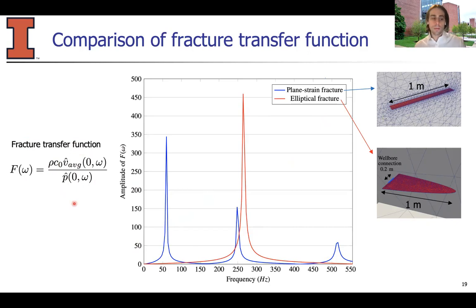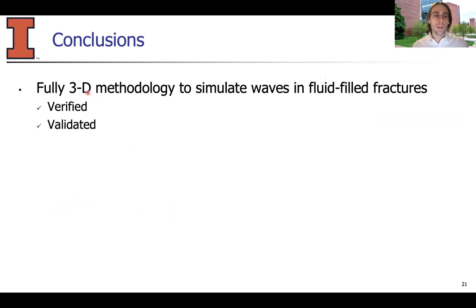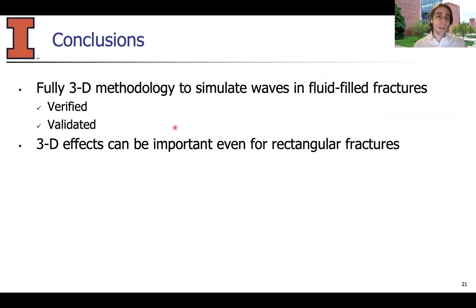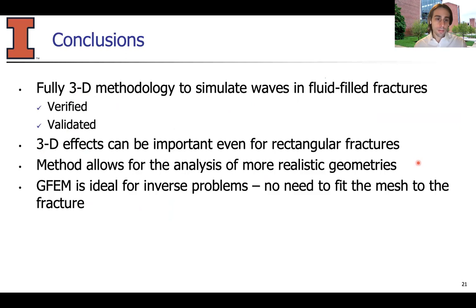And in conclusion, I tried to show here a fully 3D methodology to simulate waves in fluid-filled fractures, which has been verified and validated. It showed that 3D effects can be important even for rectangular fractures, as in the comparison with experiments. And the method allows for the analysis of more realistic geometries and boundary conditions, like the elliptical fracture that I showed in the last example.